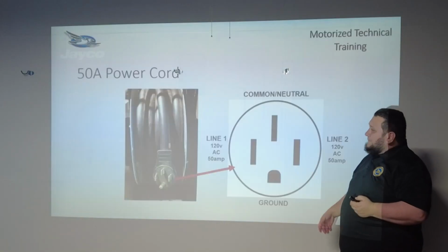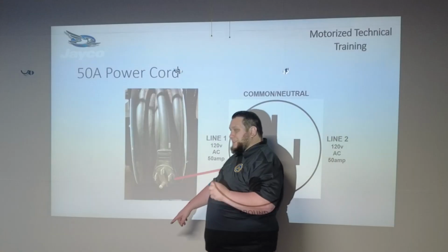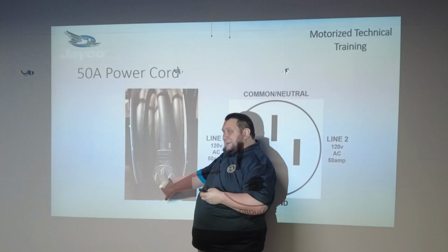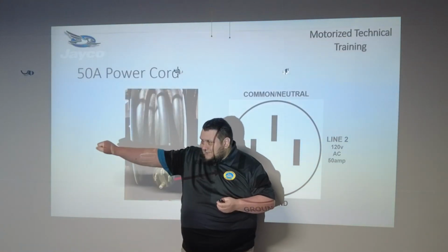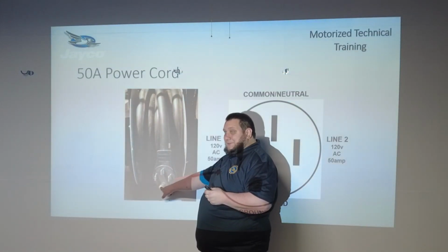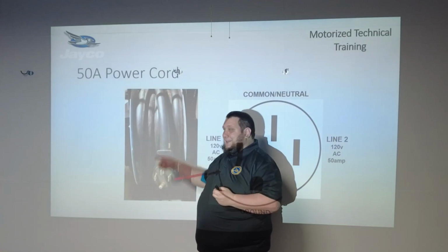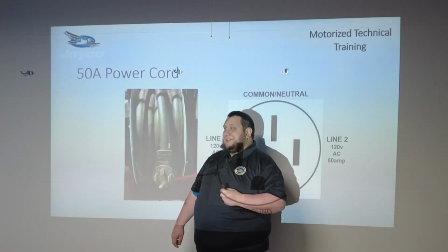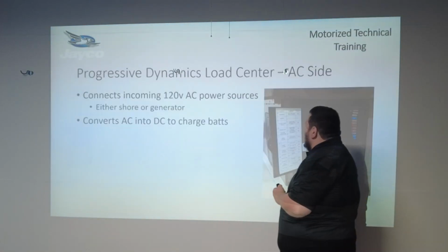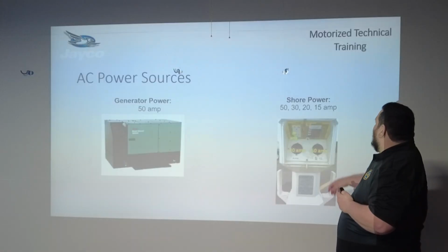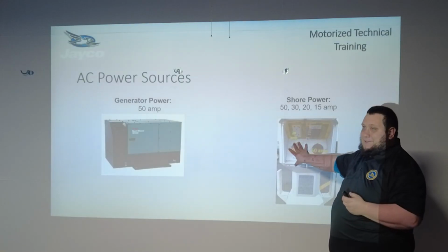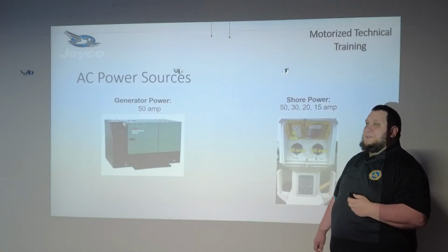Why do we emphasize the importance of that? Well, back to your question about, how do we lose a leg? If, say, I'm plugging in and I don't get it perfectly lined up when I go to push in. Well, now I've got my ground connected. I've got my two hot lines connected. Neutral isn't quite seated yet. What have I just done? I just introduced a power surge. So, as a good rule of thumb, anytime the customer or anytime anyone's plugging into a pedestal, turn that breaker off first.